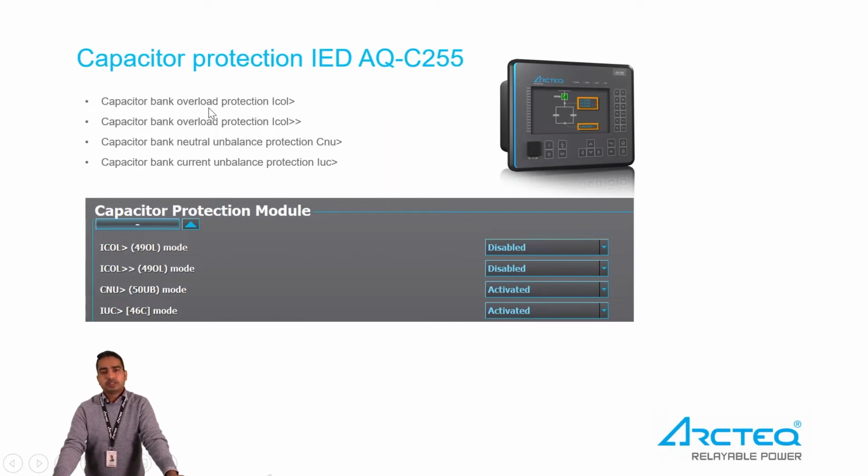Here we have 2 stages of overcurrent, basically overload protection. And then we have capacitor bank neutral unbalance protection, and then capacitor bank current unbalance protection. We will go through the IED software and learn how these settings are done and how it works on the basis of principle.